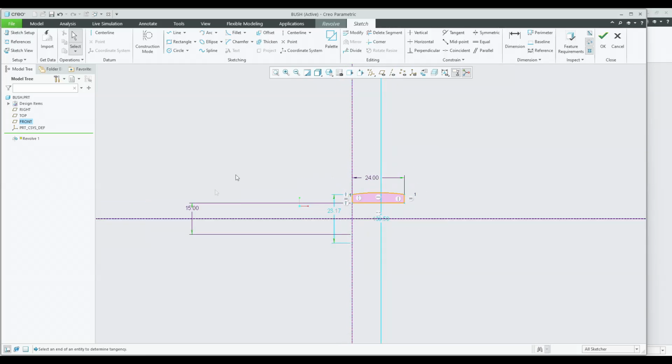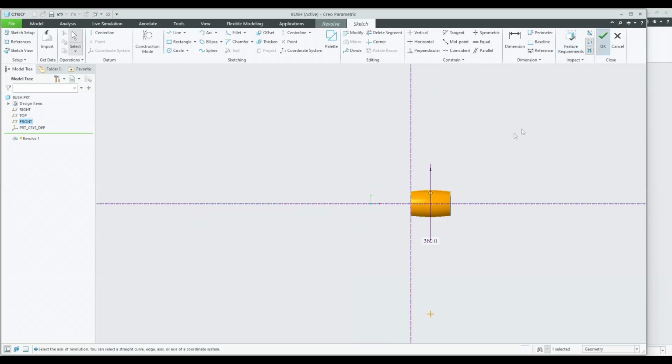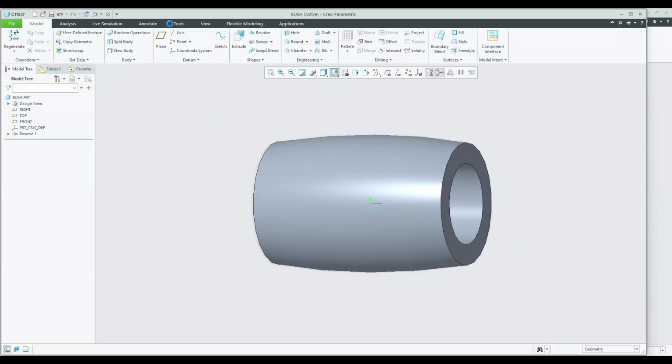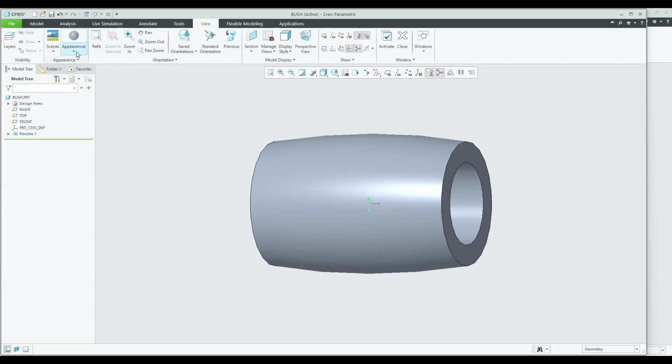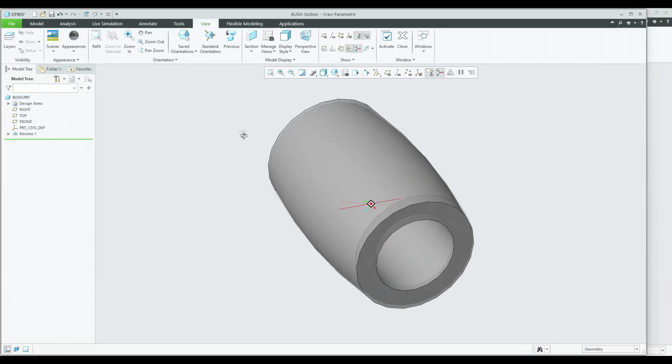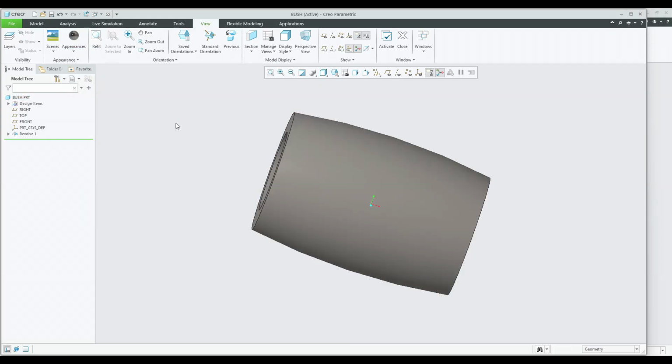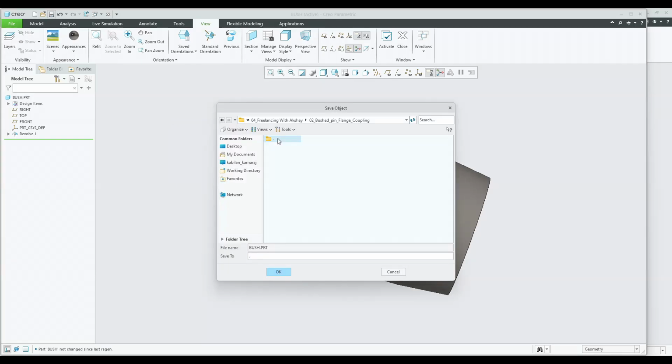I would like to modify some dimensions. This as a 10 mm and this would be a 15 mm. And I'll just click OK. So the bush has been created here and I would like to give a black color, since this bush material is going to be considered as rubber. So to identify it as rubber, I'm going to give a color of black, which is a dark one. Yeah, this looks fine.